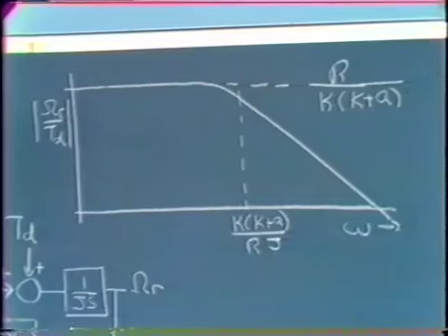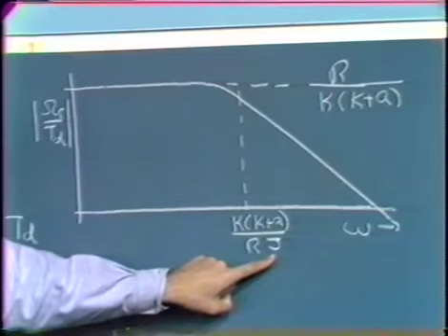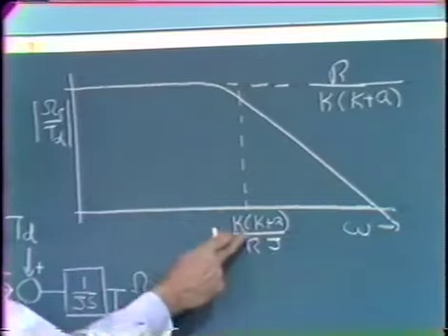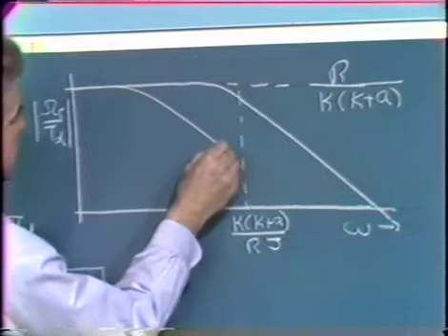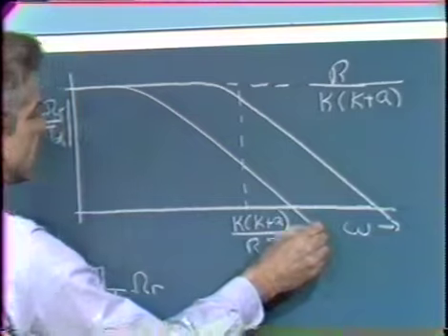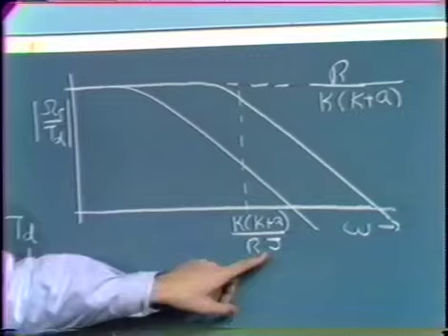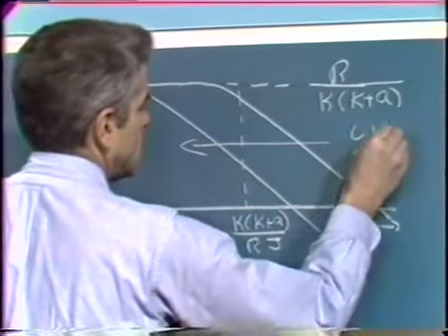So we can ensure that we have stability, possibly as much as 90 degrees of phase margin, by forcing crossover at a sufficiently low frequency through appropriate choice of J. And as we make J larger, the system performance improves. The rejection of the system gets better because an increasing J lowers the frequency of this pole. For example, we might get this sort of a transfer function when we increase J. And so this then in our Bode plot is the direction of increasing inertia.